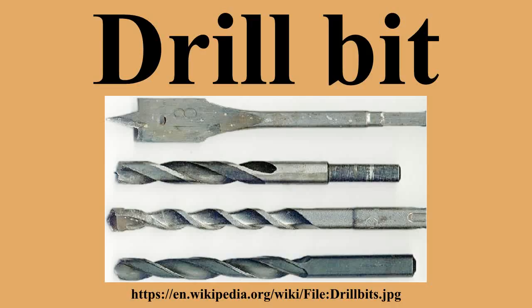Twist drill bits are available in the widest choice of tooling materials. However, even for industrial uses, most holes are drilled with standard high-speed steel bits. The most common twist drill bit has a point angle of 118 degrees, acceptable for use in wood, metal, plastic, and most other materials, although it does not perform as well as using the optimum angle for each material. In most materials it does not tend to wander or dig in.